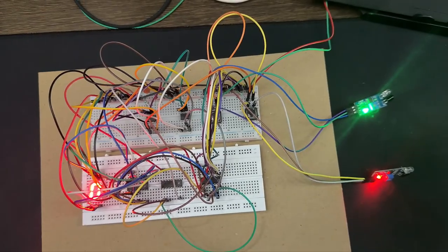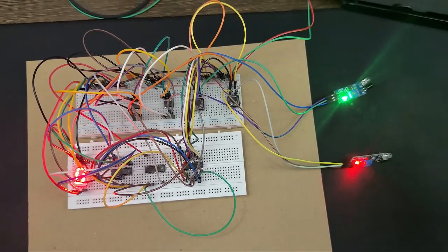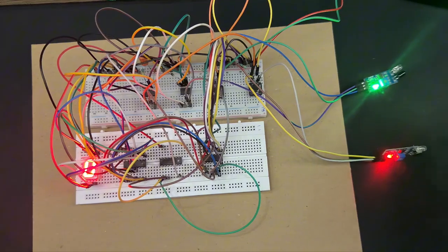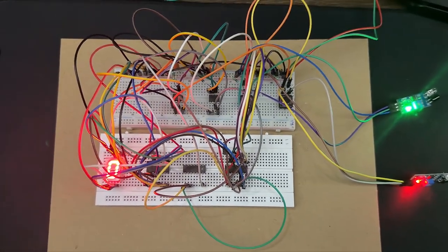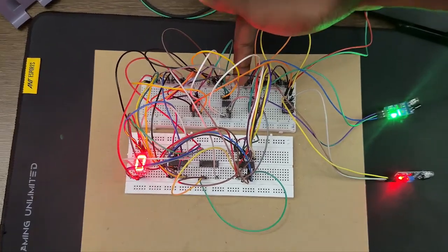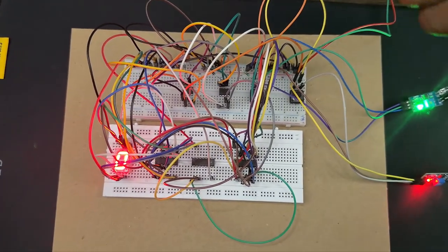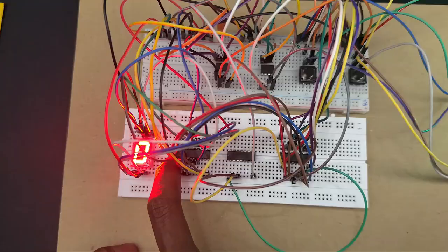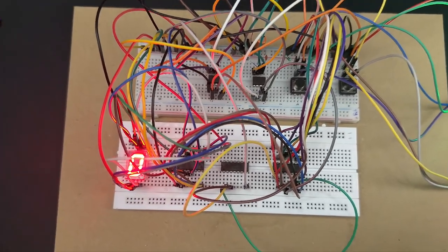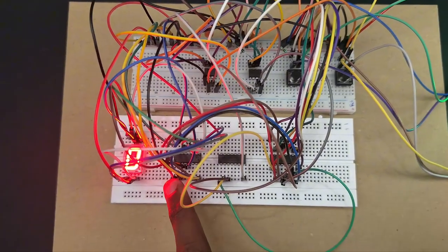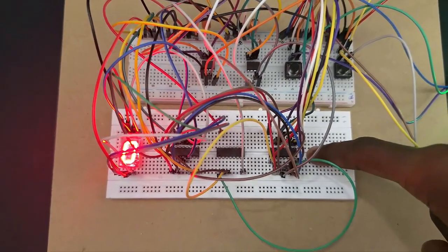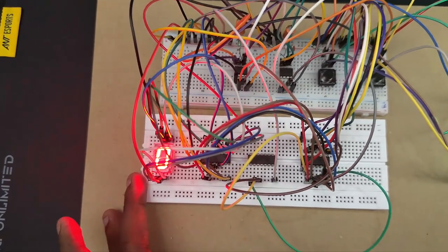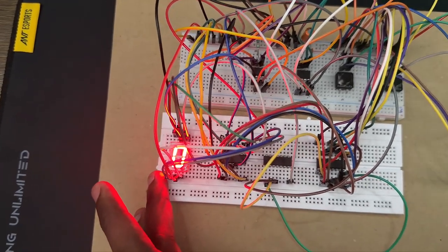Now I'm going to explain the signal flow in this model. If a car enters the parking lot, the entry IR gets triggered and it gives a noisy signal to the NE555 timer IC. It creates a clean pulse which is sent to the 74HC193 up down counter. The up down counter produces a 4-bit number, and this 4-bit number is sent to the 7447 decoder, which produces a decimal equivalent. This is sent to the 7 segment display, which displays the number of cars in the parking lot.